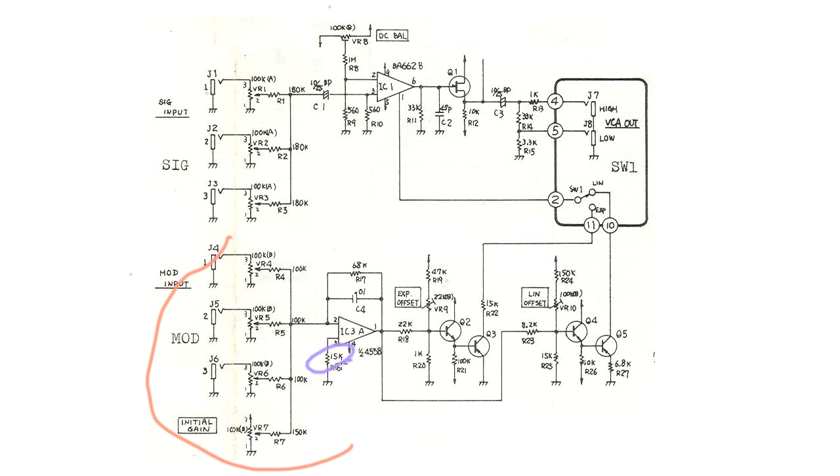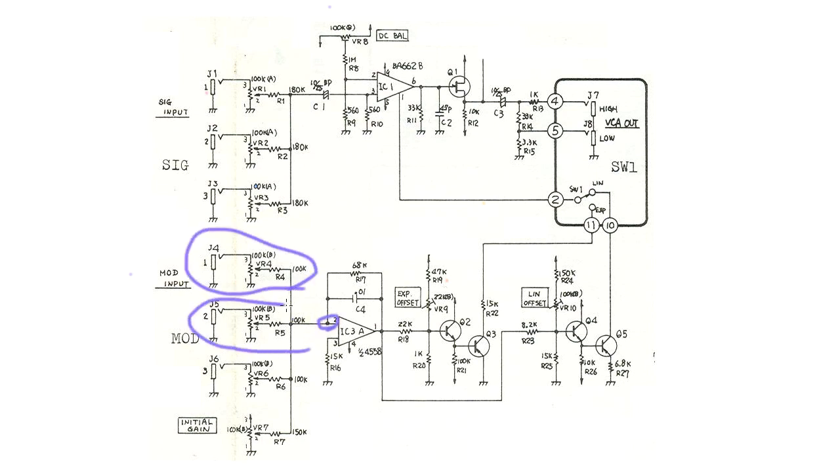For the purposes of this course, we won't worry about getting into that in more detail. This is a pretty standard thing you can find in books about op-amps and in manufacturers' application notes. Unless I distinctly tell you otherwise, I'm always going to treat op-amps as ideal. So because we have a low impedance summing node here, these various inputs are essentially decoupled.